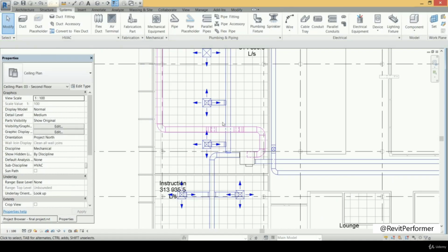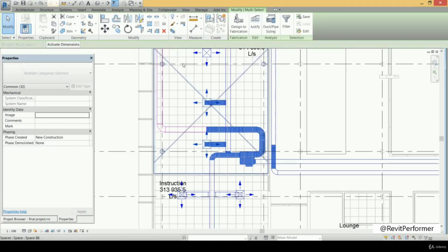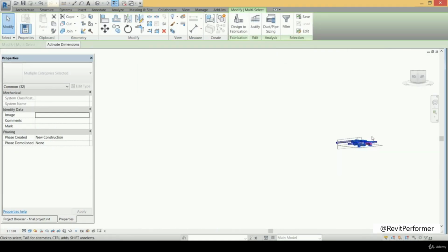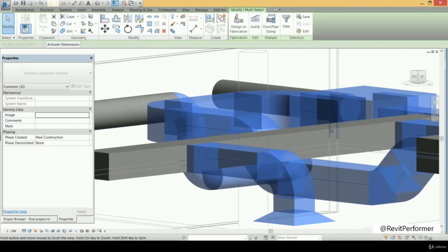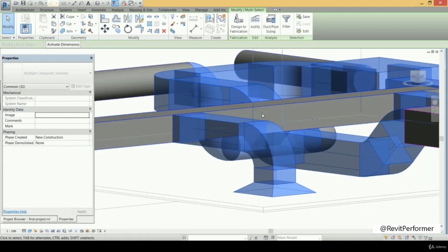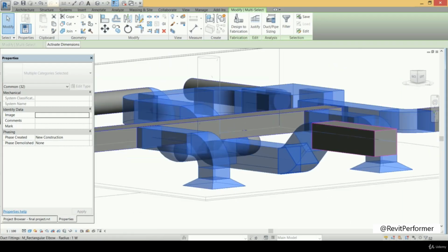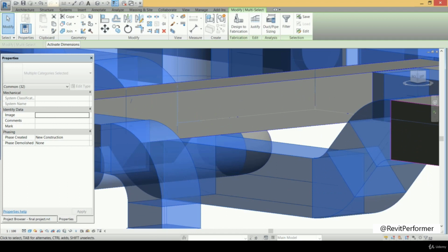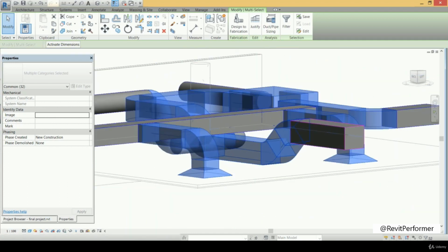All right. Now to see what we have made, we can select that part and then press on the selection box. And here let's zoom in. Very good. As you see, we managed to do it exactly. Here the return duct goes at the intersecting area with a lower offset. You can see this is the lower offset, so we have no interference between the return duct and the supplying duct, and then it continues its movement with the original offset. Very good. Now we press close.